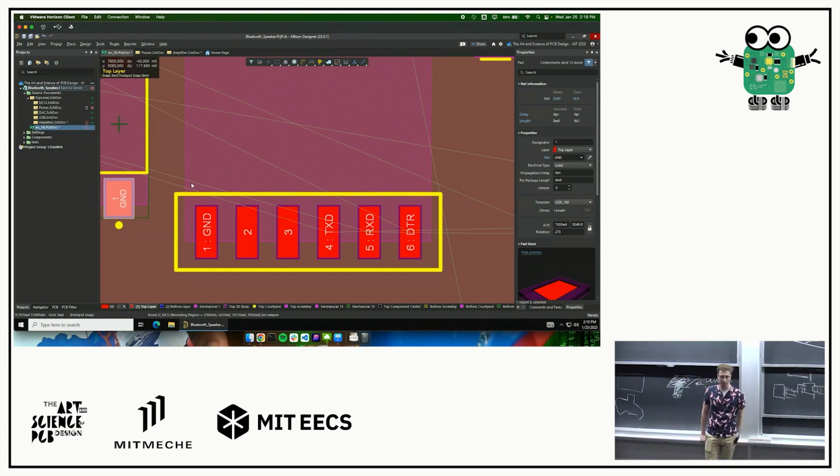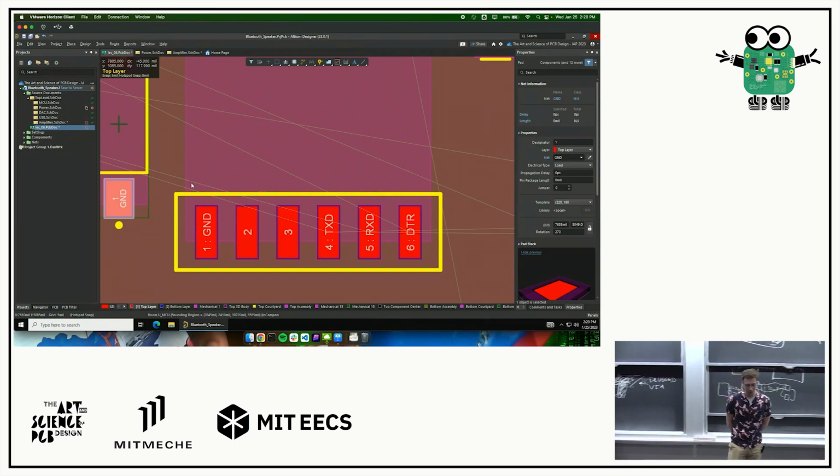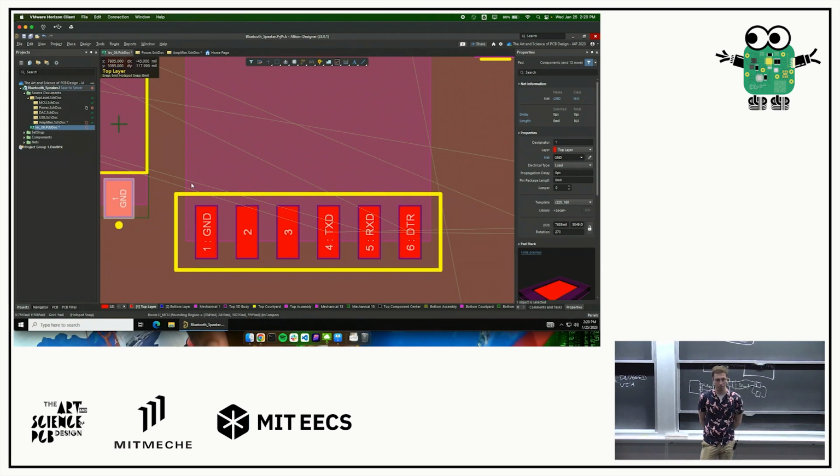One thing to consider when you're taking those tables is don't take for granted the fact that they probably don't have a safety factor. A lot of the time what those tables are doing is they're saying based on pure theoretical calculation, like this piece of copper will hold 3 amps, and more than 3 amps it will explode. So oftentimes you'll see larger traces even when the table says it doesn't need to be that thick, because if a 3 amp trace needs to be, I don't know, 10 mil, we'll make it at least 15, if not 20 to 25 because of that safety